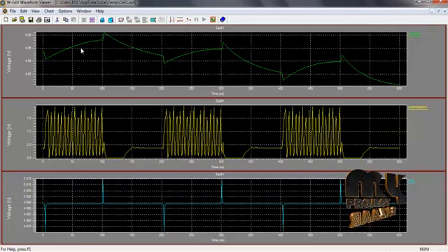If the reference clock signal is off, the sensing oscillator will be triggered. If the reference oscillator signal will be on, the sensing oscillator will be working depend on the reference oscillator clock signal.